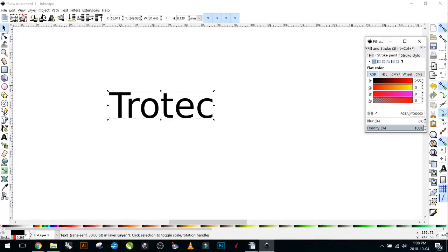So we'll go to stroke style here. And in here you have a width. You can select your unit of measurement if you'd like. In other programs, you will have to make your stroke line the smallest line possible within that program for the laser to read it.